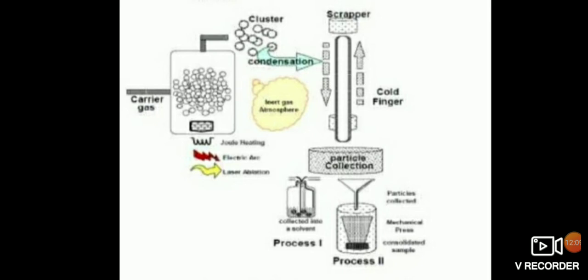Synthesis of alloys or intermetallic compounds by thermal evaporation can also be done in exceptional cases, that is, when the vapor pressures of the elements are similar. An alternative is sputtering from an external alloy or mixed target.